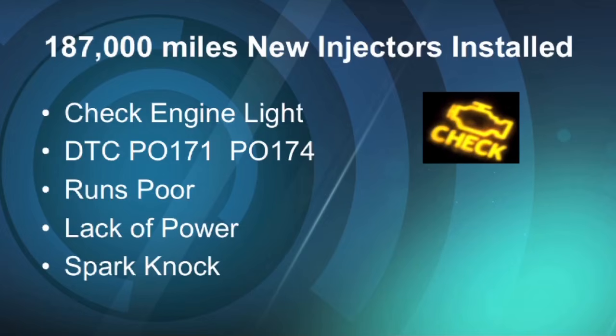So after the injectors were replaced, he then started to have more problems than he had before. He had a check engine light setting a P0171 and P0174, which means that the computer is seeing an abundance of oxygen in both banks, which could be attributed to a lean condition, causing fuel trims to migrate probably over 10% in different load cells, which sets those codes, P0171 and P0174 for bank 1 and bank 2.